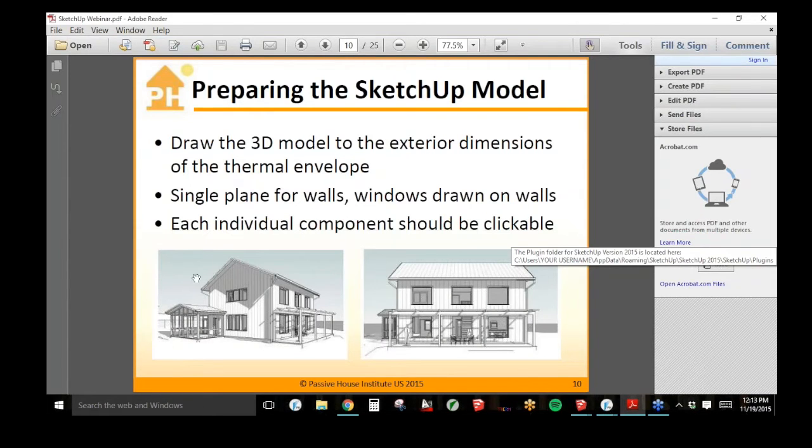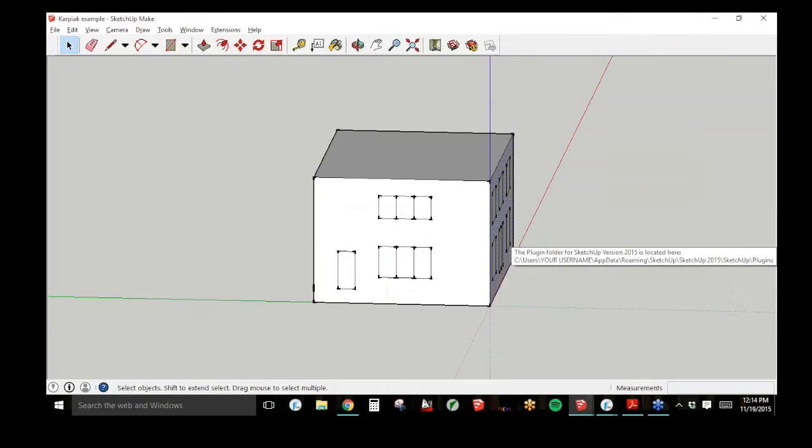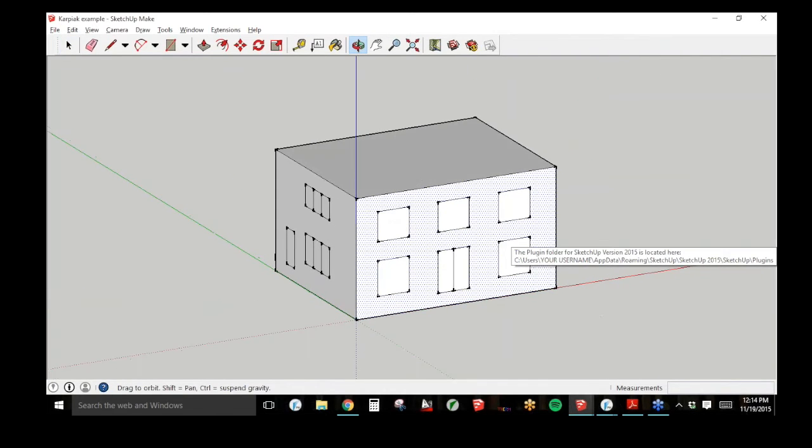So you'll also notice we didn't draw this roof. We could have, but the thermal envelope actually ended at the top of the insulation there, and it's vented with outside air. So for simplicity, we just left that roof off. Again, we could draw it in, but it would become an attached zone, and it wouldn't really affect the overall energy balance on the static side of the software.